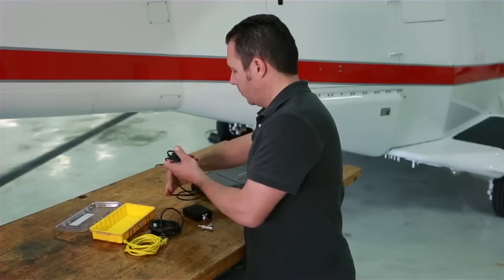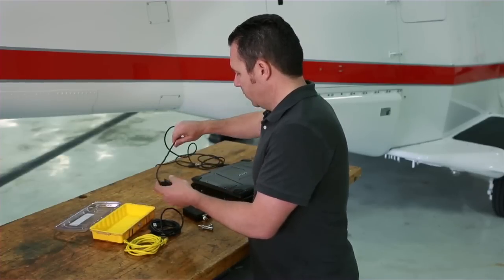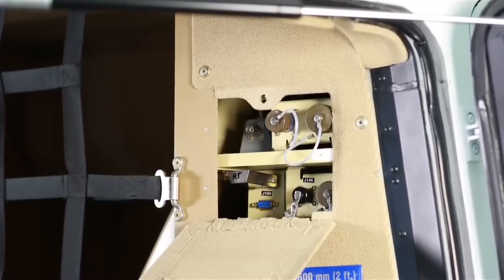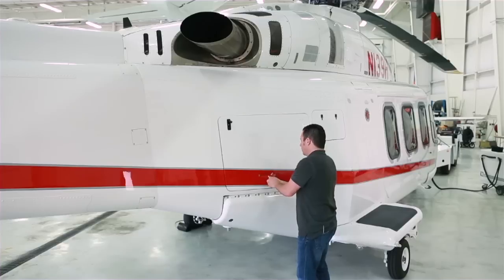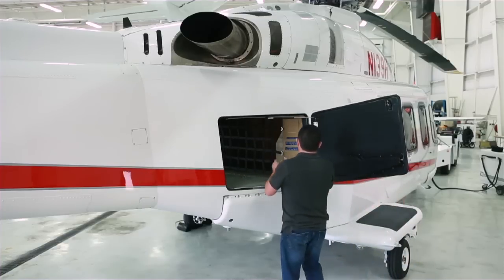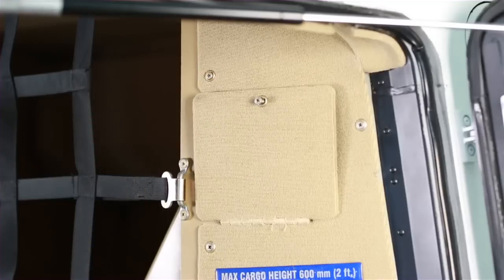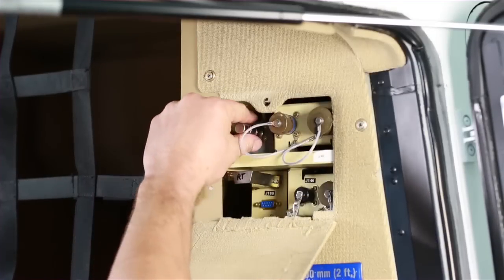Once the aircraft is set up for the load, connect the remote terminal to the LAN. There are 2 coax connection terminals on the AW139. For long-nose aircraft, both terminals are in the forward avionics compartment. For short-nose aircraft, one terminal is in the forward avionics compartment and the other is near the aft baggage area. You can use whichever connection terminal you would like.